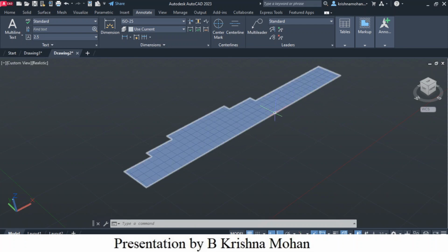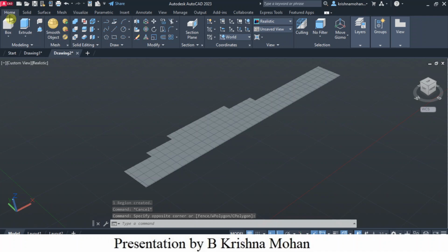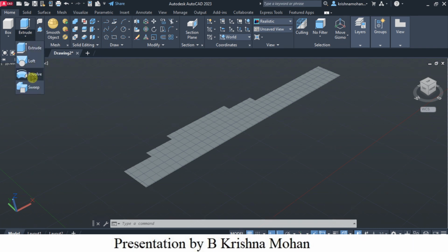This is the line which represents the axis, with length equal to 360 mm. Press escape. Now let's move to Home. Under Modeling, you have a drop-down. Under Extrude you find Revolve.